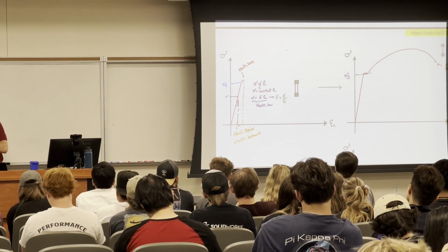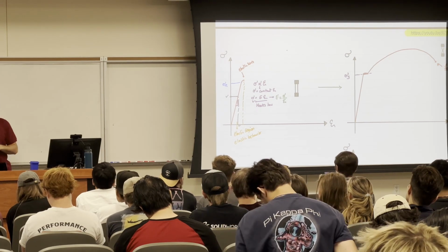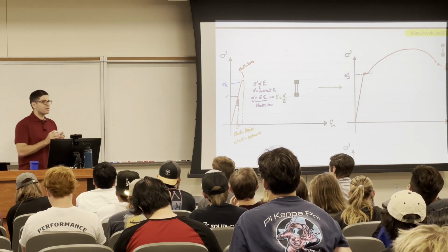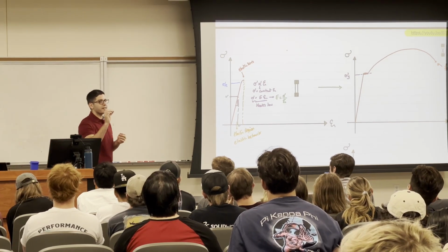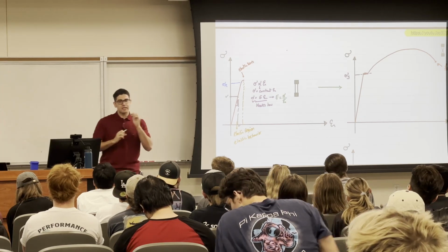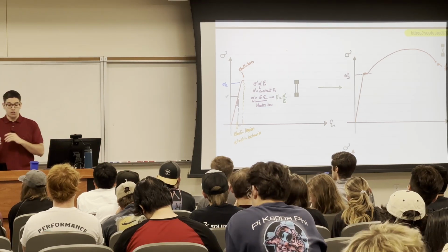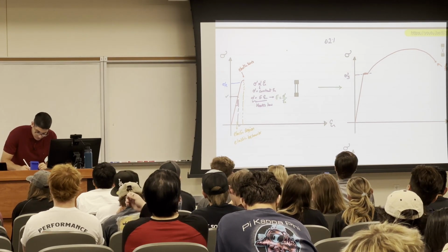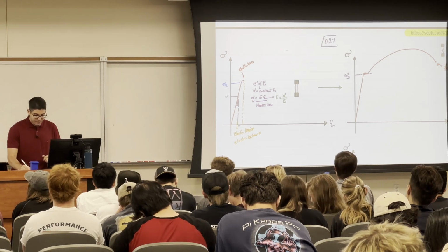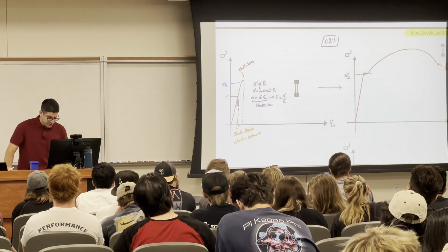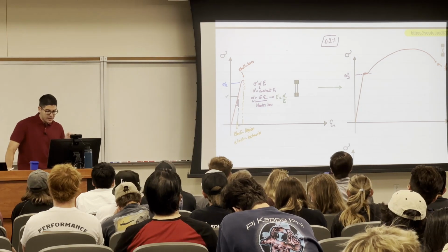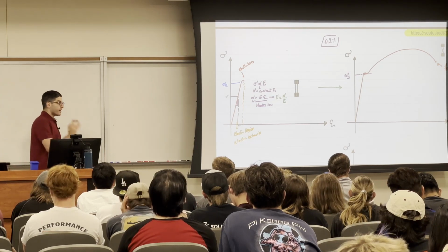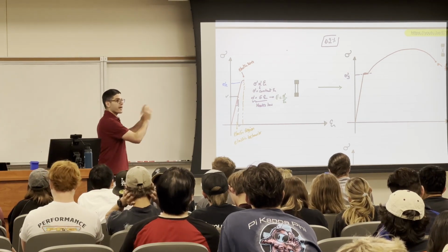So when we design our materials, we design on the yield strength. But some of you might tell me, if I design on the yield strength and the material went to the yield point, it's going to have a permanent deformation. Yeah, this permanent deformation in metals like steel and aluminum is 0.2%. That's the definition of the yield strength: the stress at which a predetermined amount of permanent deformation occurs. And the reason we choose the yield is because it's well defined and we can get it right away.